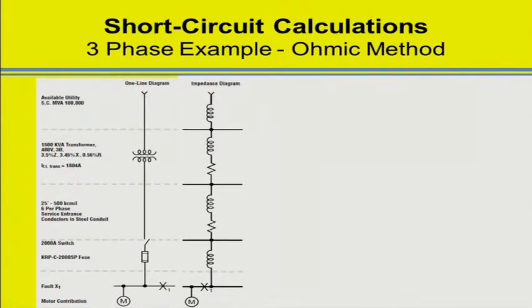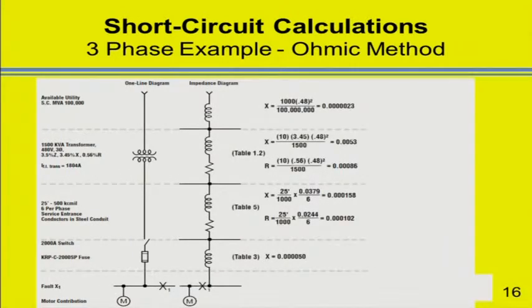And so we'll add to that and use the data then to calculate the inductance and inductive reactance characteristic then for each component in there, and the resistive component as well. So as we do all of these calculations, basically what this is doing, this is the voltage here in terms of kVA. 480 volts in kilovolts is 0.48 kV, and then multiply it times 1,000 to get it back to where it's supposed to be.